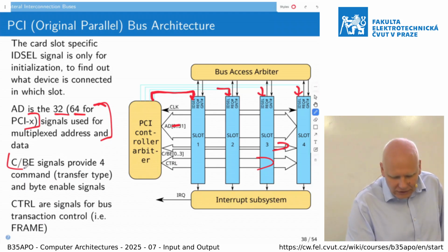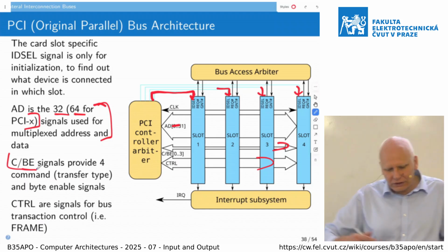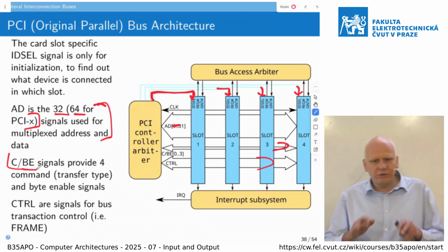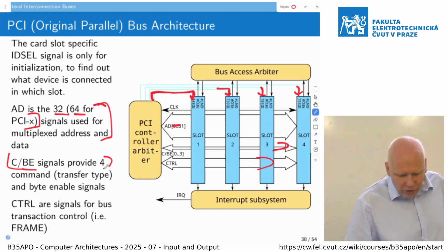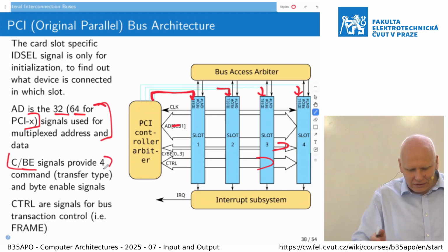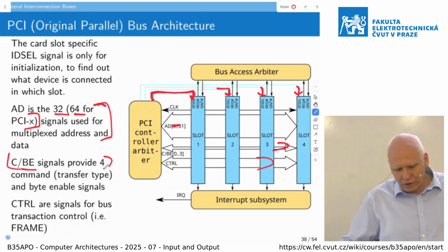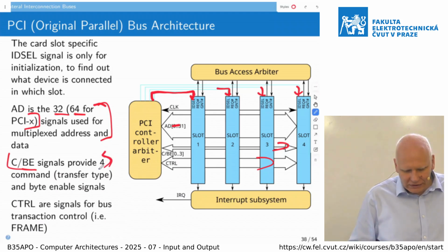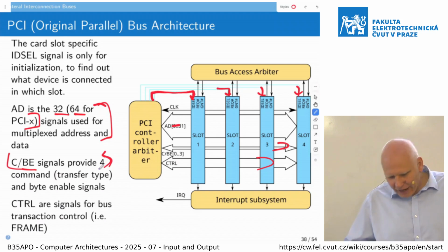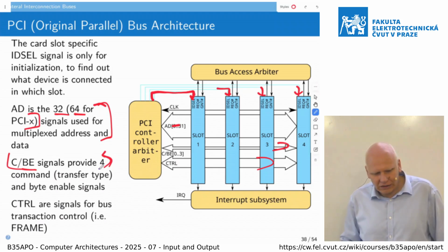Then during the data word transfer, they inform which bytes are active and which are out of the addressed instruction. So basically, if you use a load word or store word, then only the specific single signal of those 4 corresponding to the given byte in the word would be activated.